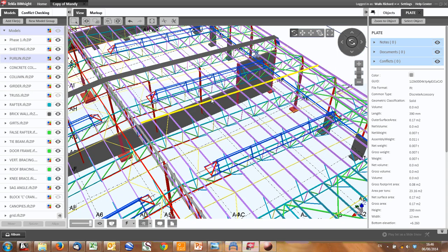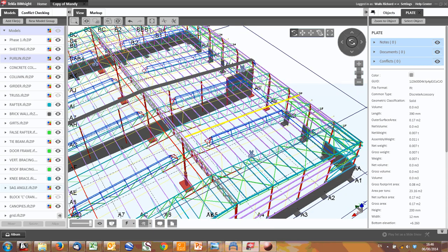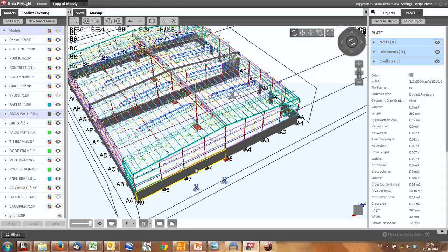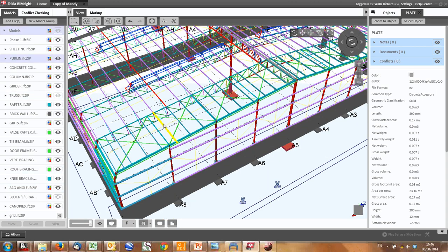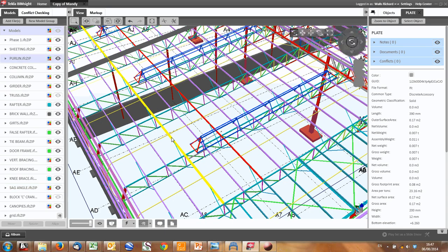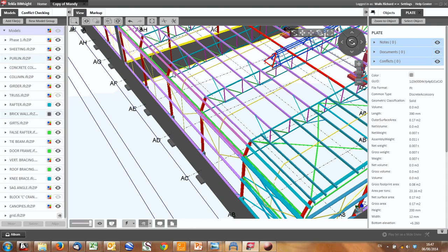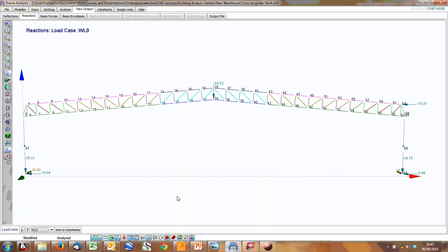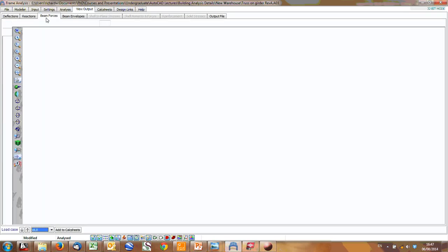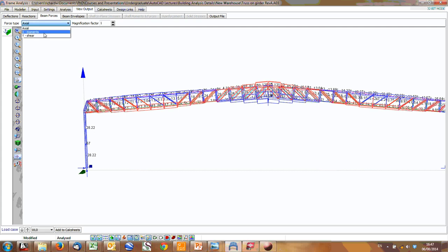But before we get there, we need some other loads. Because what we've been trying to do now is track the load. How does it go from one section to another? So we started at the outer members, so we're taking it from sort of primary to secondary to tertiary parts of the structure, as the load follows it, as it gets closer and closer to the support. So what we've done so far, we took load from girt to truss, from truss to column or to girder. And this column now we could fully design from our model. We've got enough forces and moments. If we go to our forces, we've got axial forces and moments, etc.